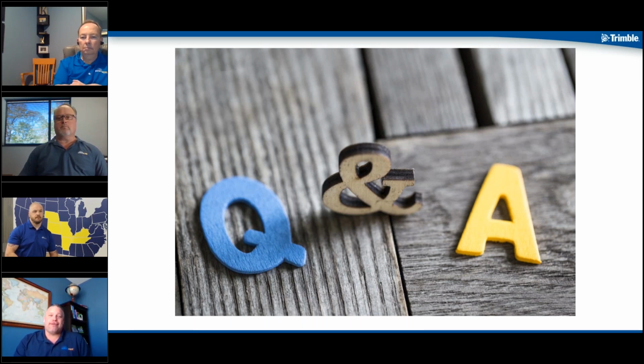And then the secondary part of that is you've got to find something that checks, or find an error that you can live with, an eighth, a quarter inch, a half inch. Find the error that you can live with, but then lock it down. Once you find that result, lock it down, set new control points from there, snap chalk lines, do whatever you can to maintain that level of control for the rest of the building.